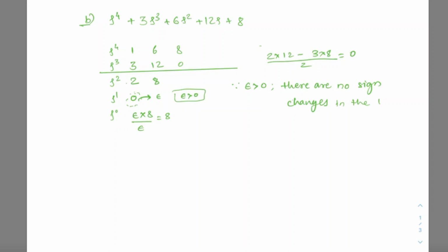If we take Laplace transform and substitute 0 initial condition, we get s square Y of s plus 4 into Y of s equals U of s. For the transfer function, let's call this P of s, since it's the plant transfer function, P of s is 1 over s square plus 4.